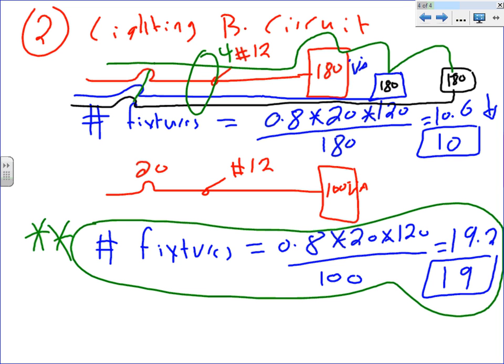Normally you have to dedicate a circuit for each unit. Especially with AC units, if it's a window, they call them window AC units, there are two rules, if you remember. If you have window air conditioning that you need to feed, these receptacles are not dedicated for it.